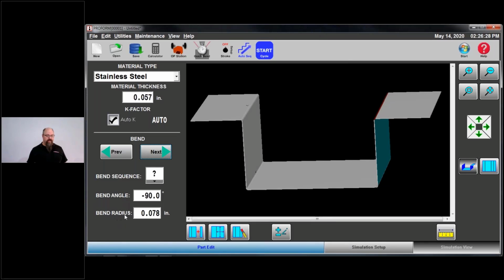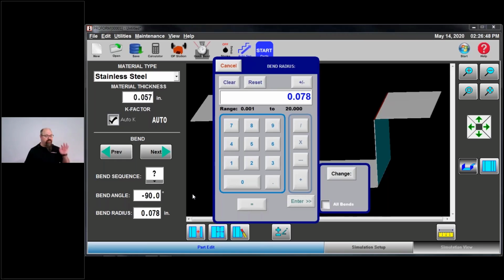Now, bend radius. If any of you watched the previous webinar, Jim went into this bend radius function quite a bit. I'm going to put out just what we use. We calculate bend radius with a formula: the opening of the V times 0.156, or 5/32.